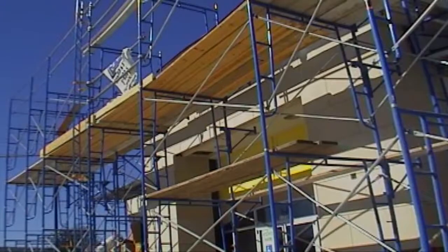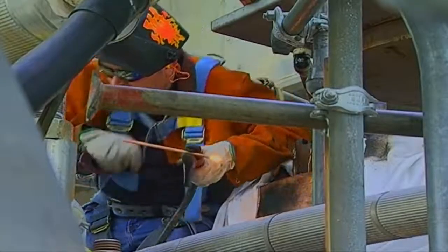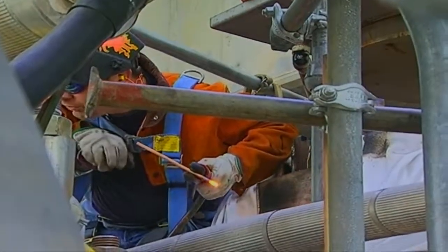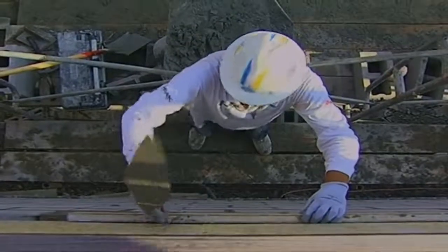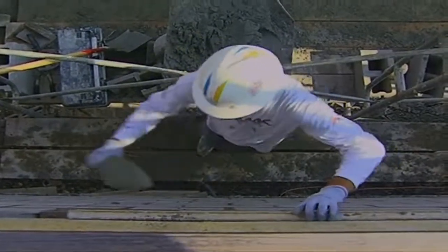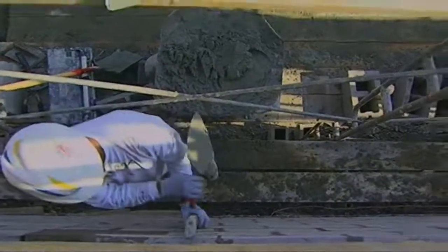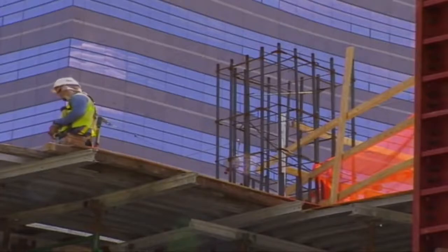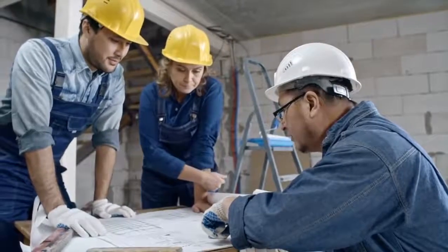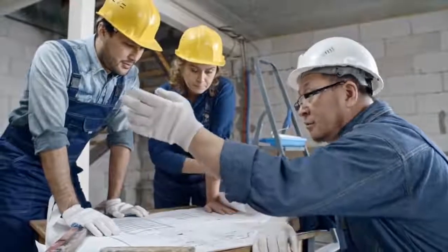Intermediate members, such as balusters or additional rails, must not be more than 19 inches apart. Guardrails should have a smooth surface and not create a puncture or laceration hazard. End rails should not extend beyond their terminal post. Cross bracing may serve as a top rail or mid-rail, providing the crossing point is between 20 and 30 inches above the work platform for a mid-rail, or between 38 and 48 inches above the work platform for a top rail. When feasible, safe, and practical, fall protection for workers erecting or dismantling scaffolding must be provided. The competent person is responsible for determining the safety and feasibility of the fall protection required.